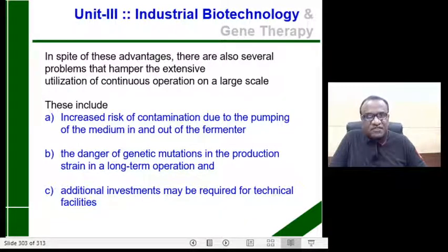So this hampers the extensive utilization of continuous mode of operation in an industrial scale or on a large scale. Number one, increased risk of contamination due to the pumping of medium in and out of the fermenter.